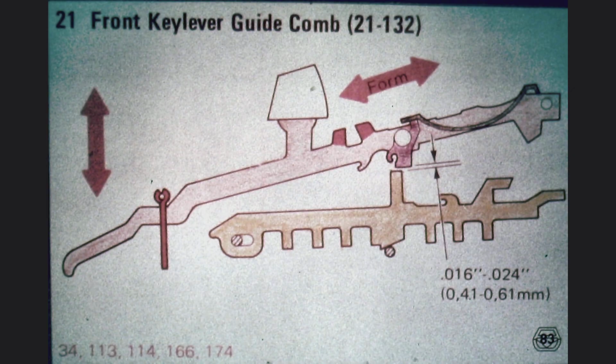Notice the red numbers in the bottom left corner of this adjustment frame. Each of these numbers represents an additional keyboard adjustment, which must be checked every time we change the position of the keylever up stop. Notice that we should have approximately 0.5 millimeter of clearance between the keylever pawl and the upper lug of the interposer. This clearance is needed to allow the resetting of the keylever pawl in an operation in which the operator has held the key depressed throughout the cycle.